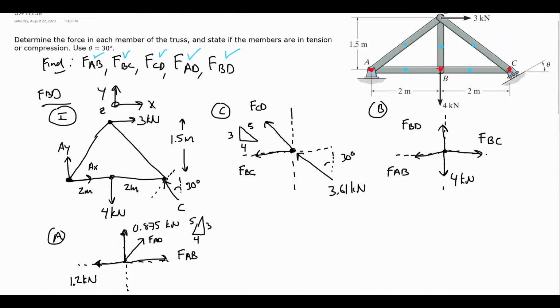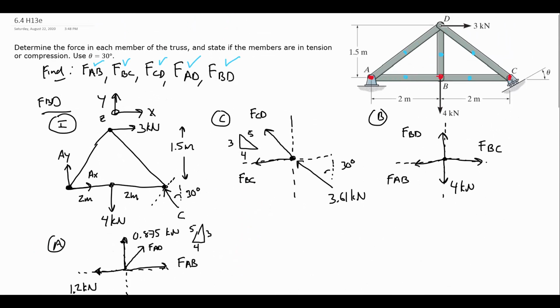And notice we did not make the free body diagram for pin D. We did not need to solve for our unknowns, but the 2 equations that came out of that by this point would also have been redundant and should give us 0 equals 0 or something very, very close, due to maybe just some rounding errors. So drawing D and checking that to make sure those equations are true is not necessarily a bad idea to check your work to make sure everything's consistent. However, there's no new unknowns being introduced in those two extra equations.